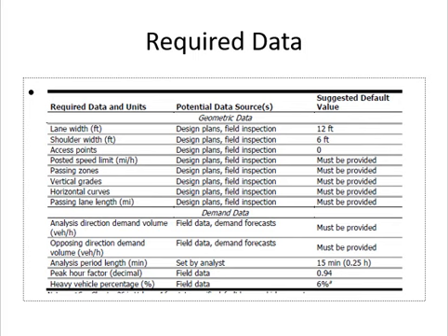So what is your analysis period? You need to know volume in both directions. You need to know your minimum analysis period, the period which you take for your flow rate, and I told you earlier as well, we normally take it 15 minutes. Then peak hour factor and the percentage of heavy vehicles. In some cases default values are given. So if it is not given, or you cannot find it out, you can pick the default value.